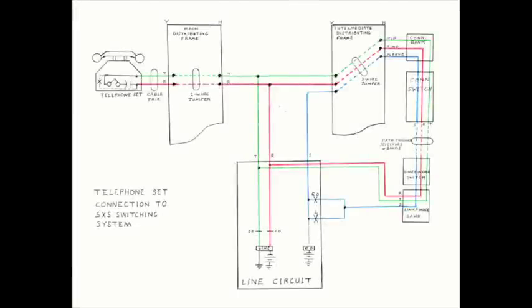Telephone sets are connected to a pair of wires called the tip and ring, which link into the central office via drop wires, distribution cables, and feeder cables. The feeder cables terminate on the vertical side of the MDF, so there is a physical 2-wire connection between the telephone set and the main distributing frame in the central office.